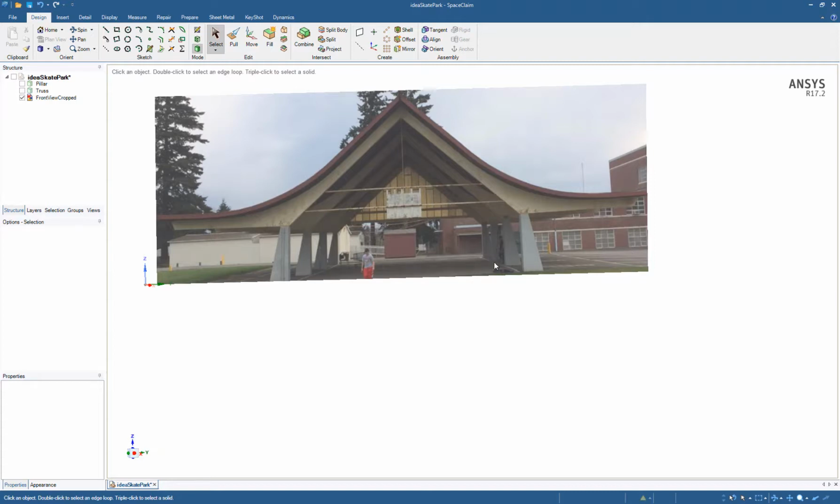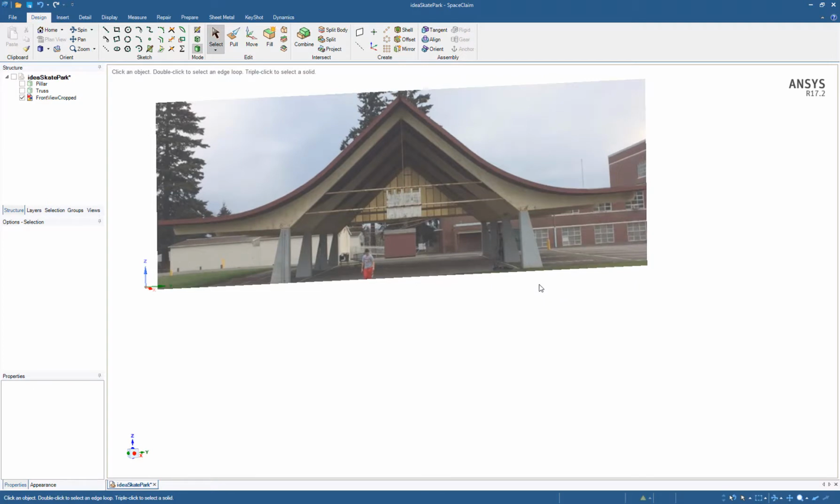So in this example, we measured some of the basic dimensions that we need to create this. And if you look at the pillars and the truss, you'll notice that it's certainly evenly symmetric, as if you divide it right down the center here. So we certainly only need to build half of it. And what it looks like is that we can actually get away with just building maybe 1/8 of it. There's 8 pillars and truss on each side.